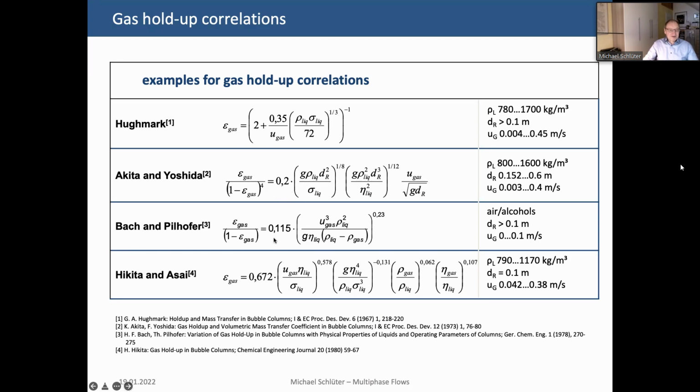These parameters here, for example, this is an empirical parameter, this is an empirical parameter, they have been adapted with experiments that have been done somewhere in the laboratory under very special conditions. And if you change the conditions to your own system in industry with a certain chemical system, certain gases, other temperatures, other pressures, then you don't know if these constants that have been adapted are still constants.